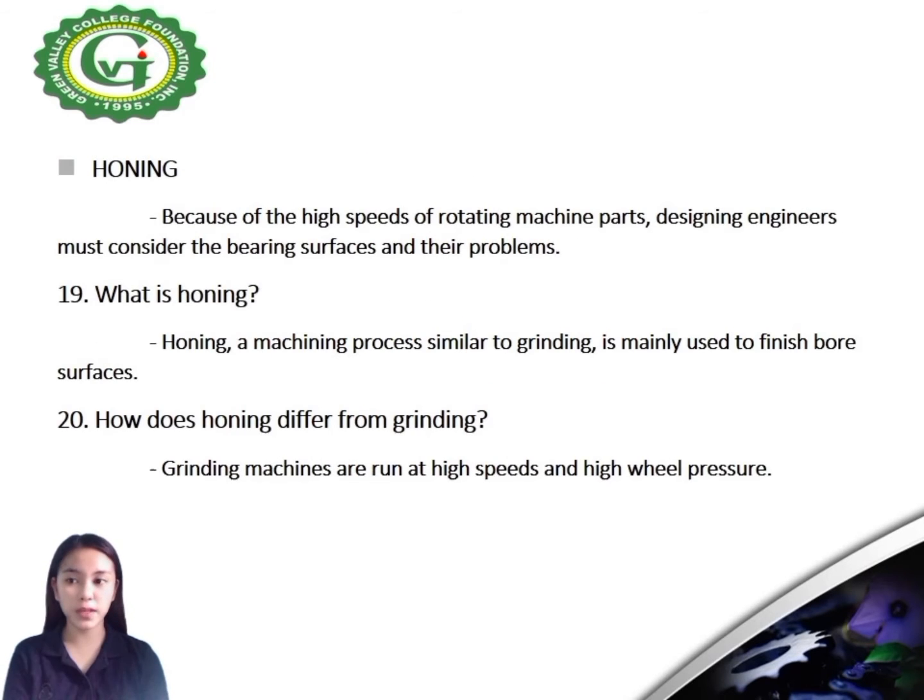Okay, let's proceed to honing. Because of the high speeds of rotating machine parts, designing engineers must consider the bearing surfaces and their problems. What is honing? Honing is a machining process similar to grinding. It is mainly used to finish bore surfaces.